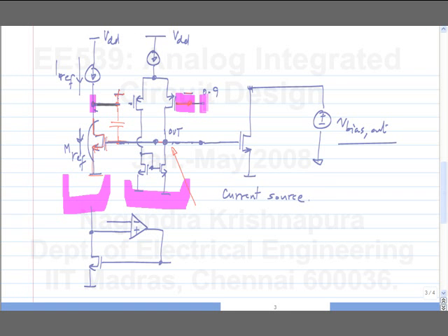See, the output voltage is on the lower side, right? It's the NMOS gate voltage, and the input voltage is in the middle. So for the input voltage, it doesn't matter. If you look at it, with a PMOS input op-amp, the output can swing low but not very high. Similarly, with an NMOS input op-amp, the input can swing high but not very low. So if your reference transistor is PMOS, you use an NMOS input pair, and if your reference transistor is an NMOS, you use a PMOS input pair. So let's say I didn't want to do this.